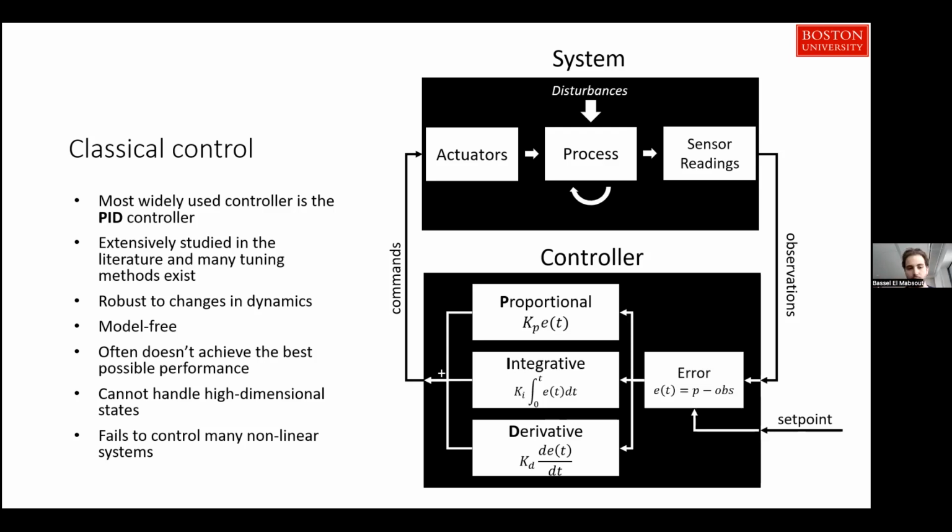So it's really used everywhere, but it has its limitations because it's so simple, because it's just these three terms that we're applying everywhere. It doesn't mean it can control all kinds of robots. You cannot use a PID controller, for example, to control a walking robot, because you need to plan how each joint needs to go so that the robot doesn't fall. And your goal isn't just to minimize some error, it's to not fall, for example. This is a high-level goal.